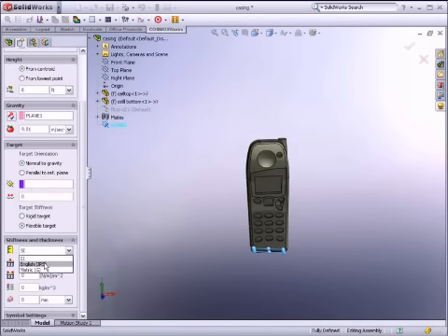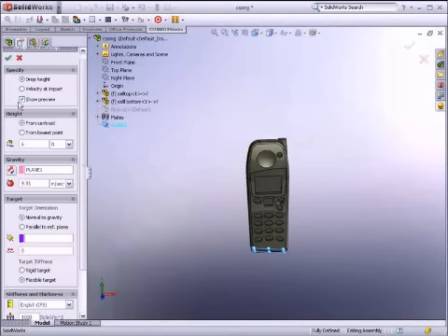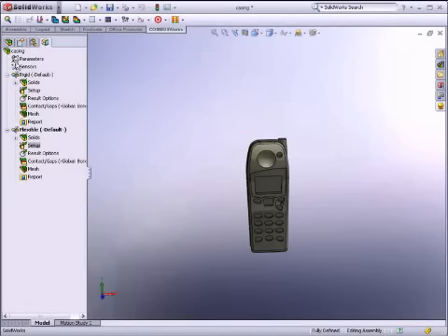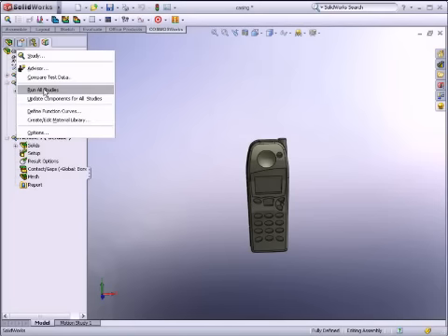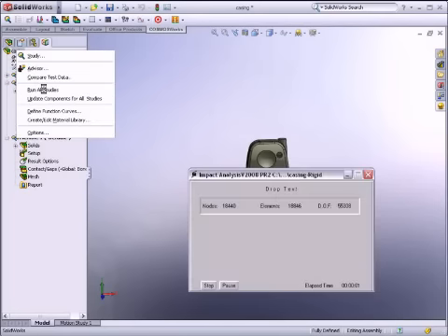For this drop test setup, we will select a flexible target and define the stiffness of the surface, along with the mass density of the impact layer. For instance, the physical properties of carpet flooring. We will also add an analysis definition to examine a flexible target that is stiffer than the previous definition. For example, hardwood flooring. We'll skip the process to save time in this demonstration.